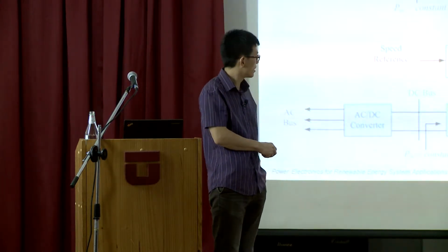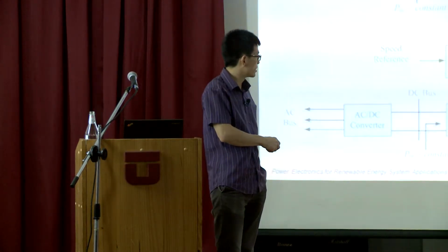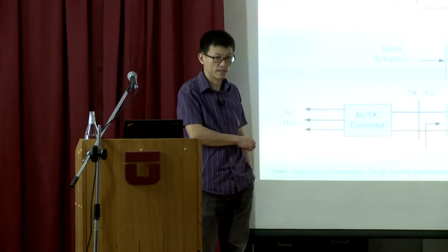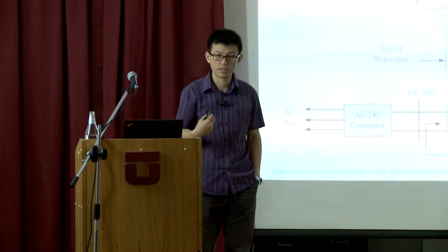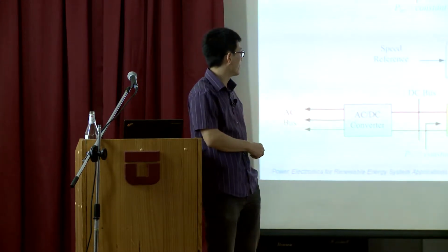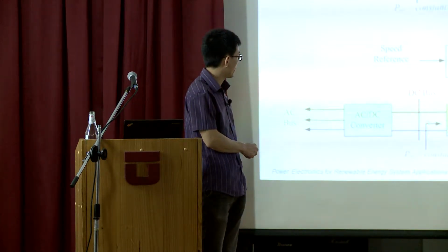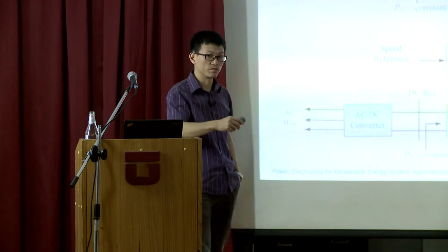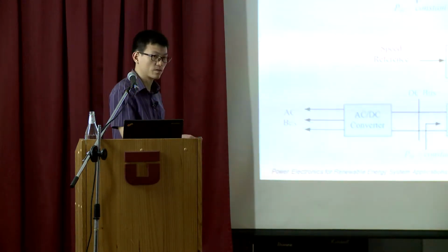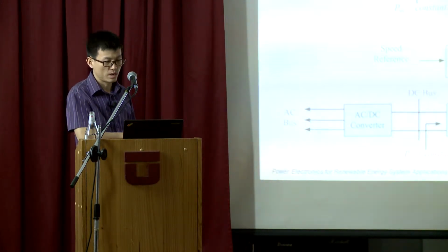Another one is the AC drive. What's happening for the AC drive is that you produce torque and spin the load. If the load and speed are constant on the load side, then on the DC power side you draw active power, which stays constant. So it is the mechanical power, essentially the active power. If the machine draws such an amount of active power, the DC bus should supply such an amount of power. So if the load is constant and the speed is constant, this will be a constant power load. These are the two main constant power loads.